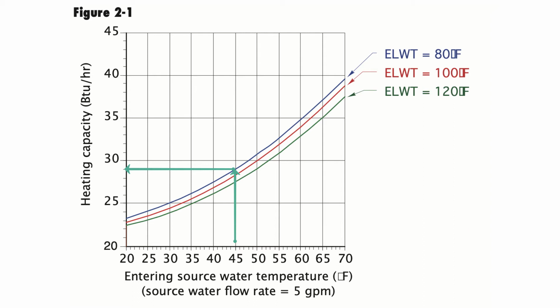This is important in the designing of the hydronic radiant floor heating system to ensure that in order to retain peak efficiency, the heat medium must be as low a water temperature as possible, typically a source water temperature between 90 and a maximum of 115 degrees Fahrenheit. If the load demands a water supply temperature greater than 115 degrees Fahrenheit, then you will need a two-stage system whereby a boiler will come online to pick up where the heat pump is left off at 115 degrees Fahrenheit.